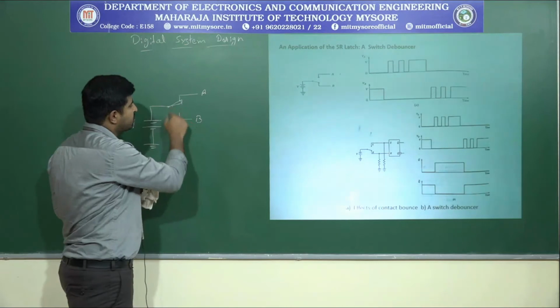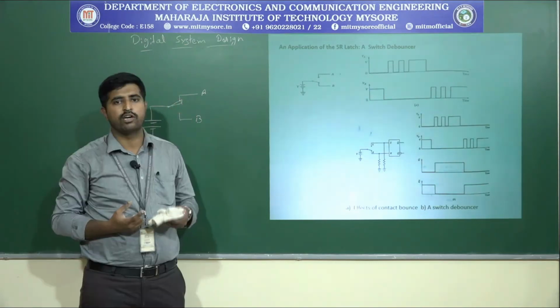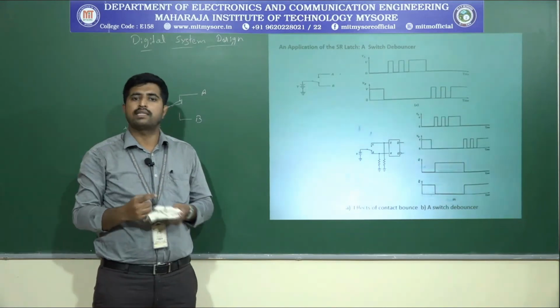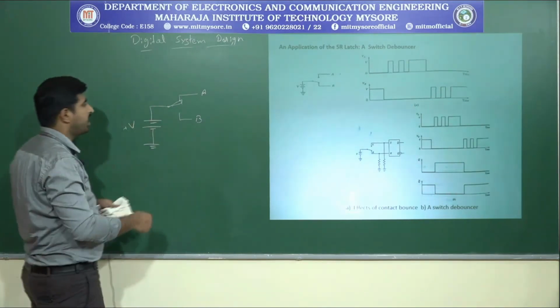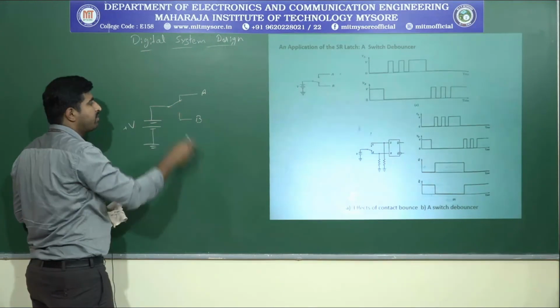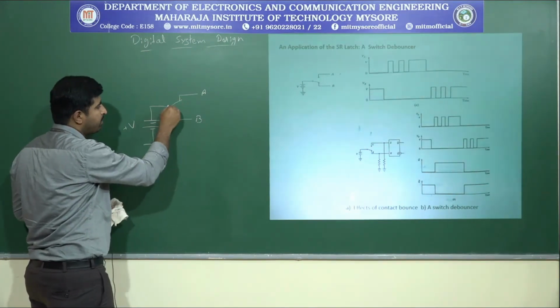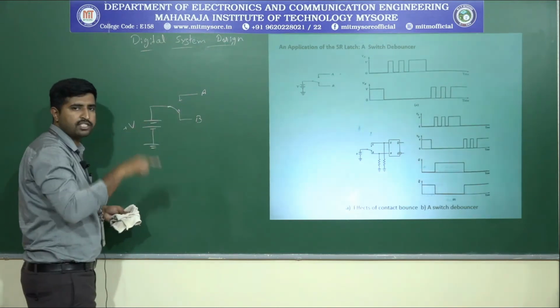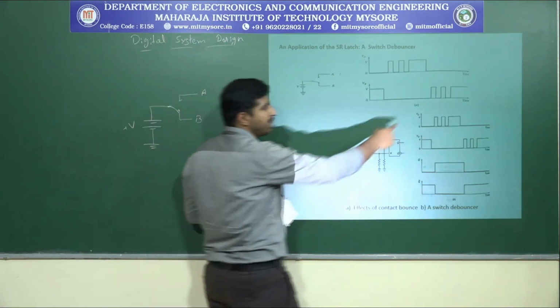Due to these switch bounce operations, we cannot predict whether the output is 1 or 0, and that is the problem. The same problem happens again when we move the contact from point A to point B. Again, due to the spring actions, the bouncing actions repeat here also.